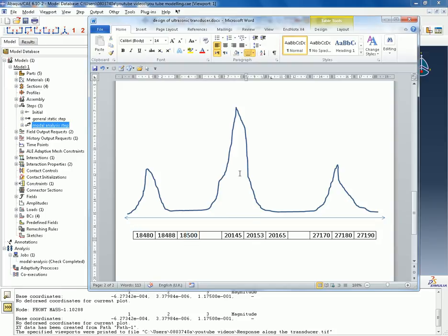So here it's going to explain exactly, if you select the bias parameter to be 1, it's going to distribute the number of points equally over the range of frequency I've selected. If you increase the value of the bias, then the number of points being calculated on the limits of the frequency will be higher than in the middle.